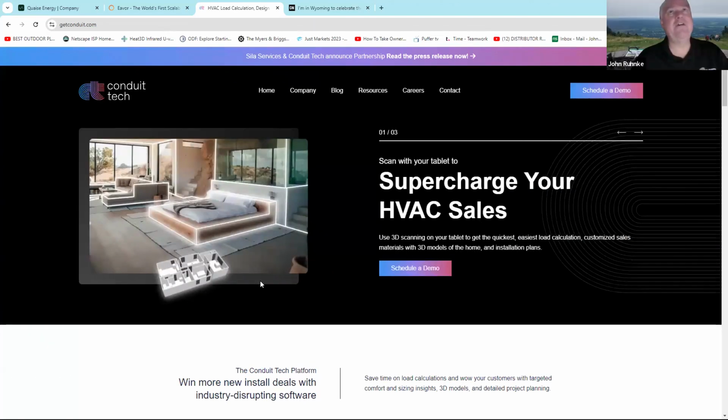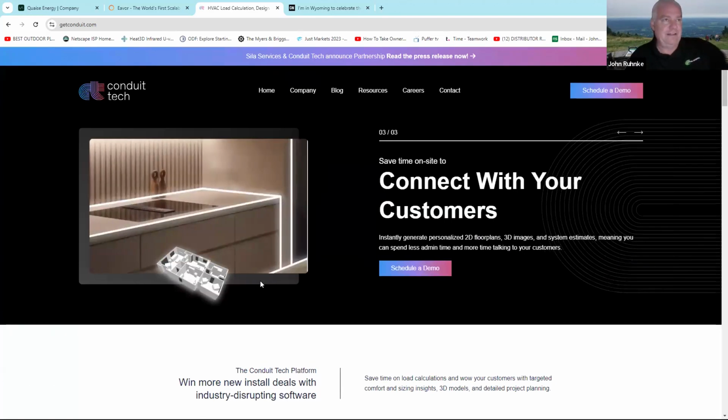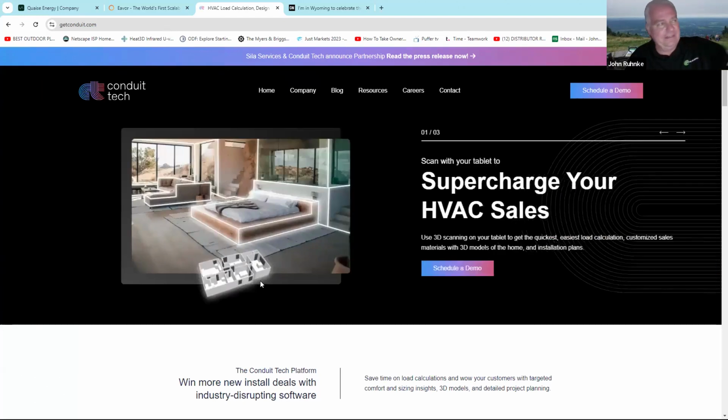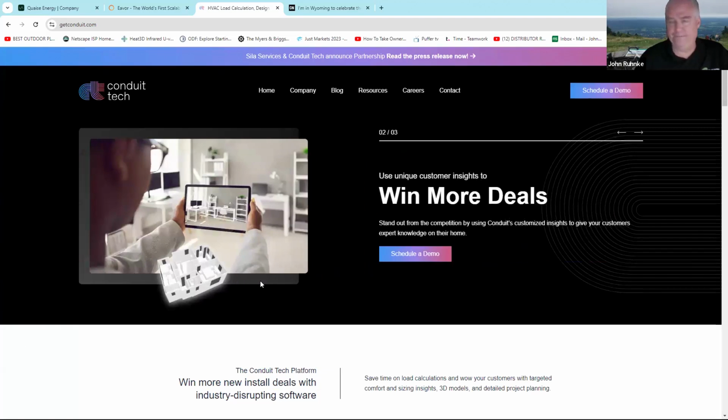Well, okay, how it does it is our air source heat pump. There's EVI, enhanced vapor injection. Enhanced vapor injection is a third heat exchanger, which cools the refrigerant even further, making it even colder. So the refrigerant goes outside and into the evaporator, and it's even colder, and so it's grabbing energy from the air. And this energy it grabs from the air is free.